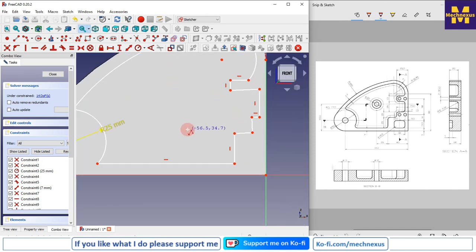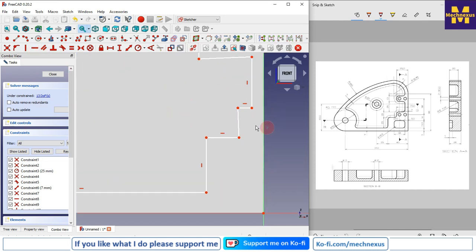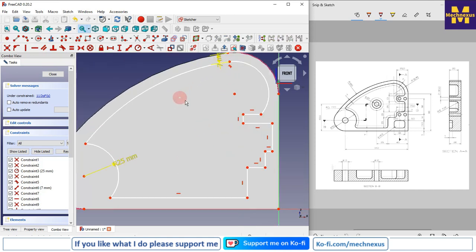Now I will select this line, this one, all three, and make it horizontal. I think go one by one. So select this one and give horizontal, and this one would be vertical. So this is our very rough profile, and now we will constrain it.